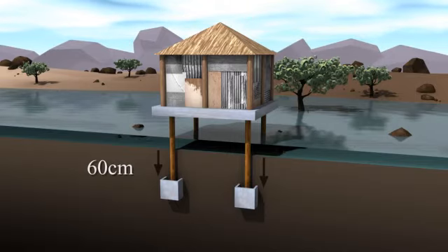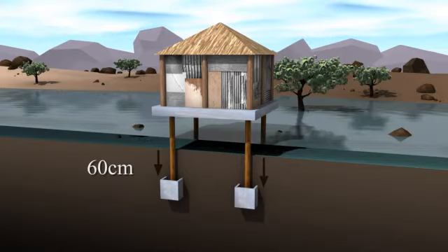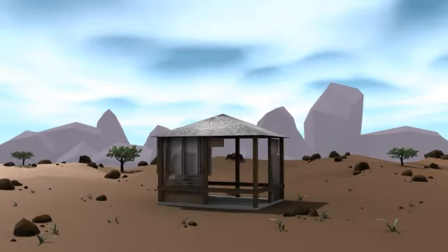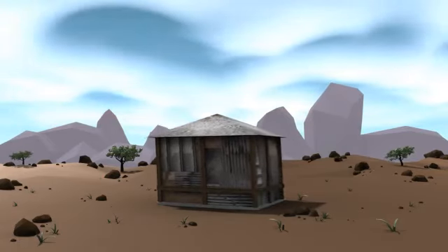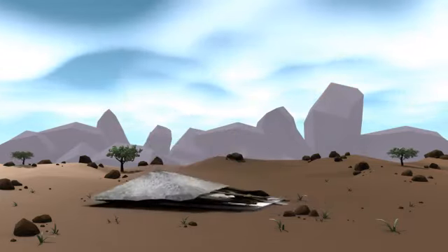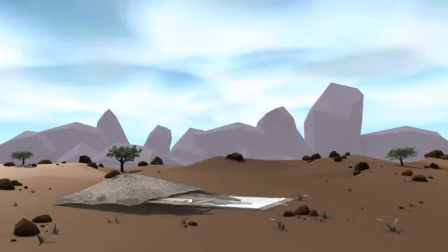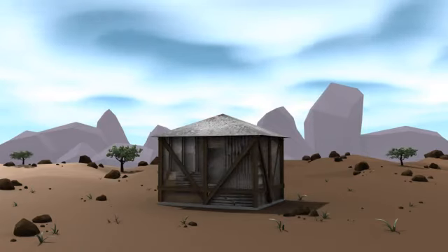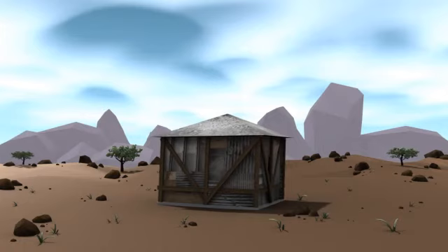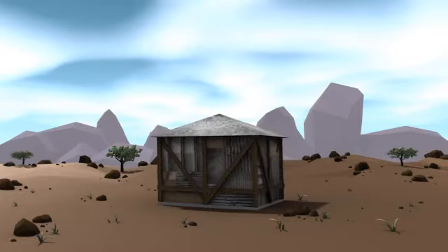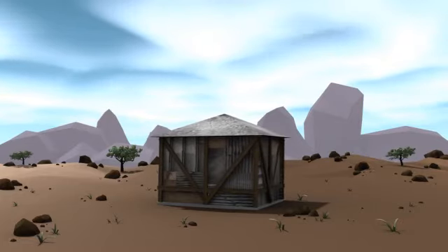of the building. The shelter's stability is also linked to the construction of the walls and its level of reinforcement. A simple wall structure without reinforcement is at risk of damage and collapse due to side pressure resulting from wind and flood water. The bracing of a wall structure allows the increase of structural resistance. By placing a diagonal connection within the structure frame, it is possible to increase the structural capacity to withstand side forces that might result from high winds or flood water pressure and weight. This will help in reducing the risk of collapse or severe damage of the shelter.